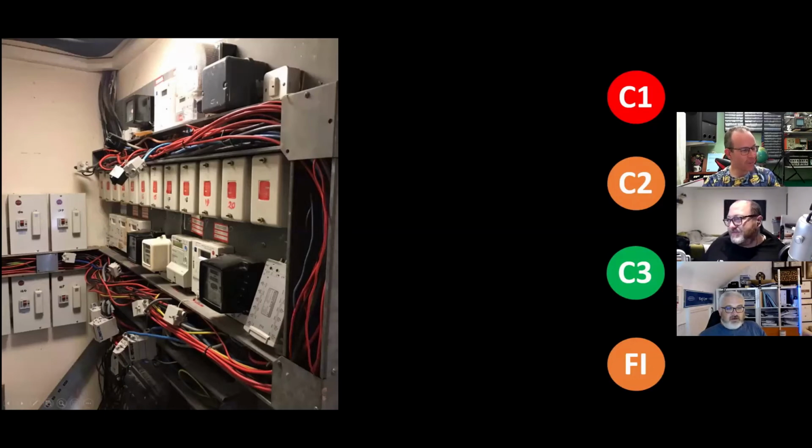Just to add to Mark while he's saying, a core cable under a joint will never be tested. There is currently talk amongst the HSE and the DNOs, because we are all taught that there should be an electrode at every single joint. What they're doing is putting coils of wire and calling it an electrode. Fine, but how that actually garners any real impedance sat underneath a torpedo joint is beyond me. So I think that issue is going to debate on and on. You can probably tell I have done lots of talking to the DNOs about this, only because I'm working on some DNO investigations at the moment for work.